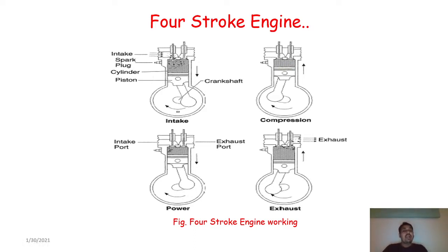So during suction only air will come inside the engine cylinder, and during compression only air will get compressed. Because of the compression process, that air is compressed within a very low volume, within this particular space itself. That's why its temperature increases.